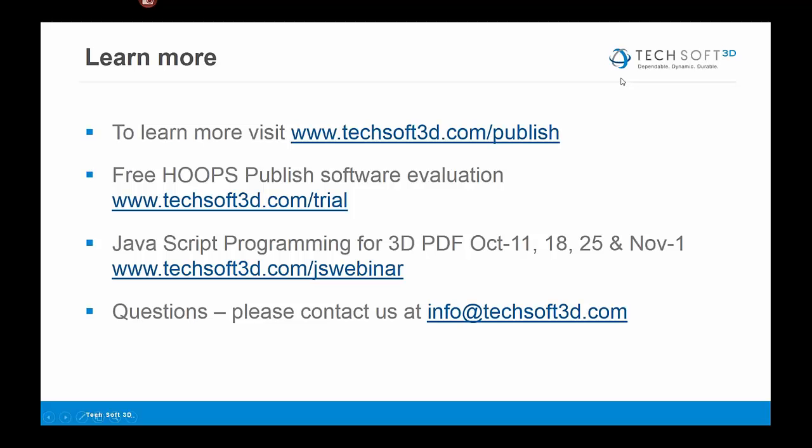Hoops Communicator can author to other file formats as well, so you're not just limited to this web viewable form or this PDF, but you can export to a STEP file, for instance, or a thumbnail image, or a large rendered image. So there's a lot of opportunity there to create different deliverables using Hoops Communicator, and that's just something that you would build a web infrastructure around.